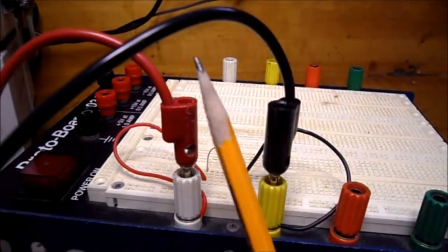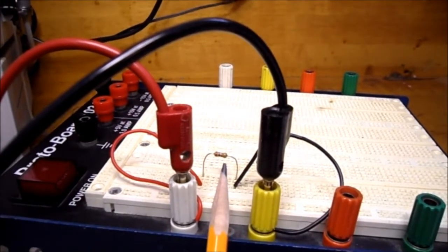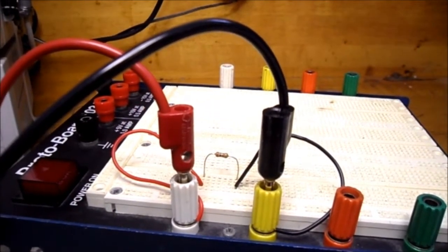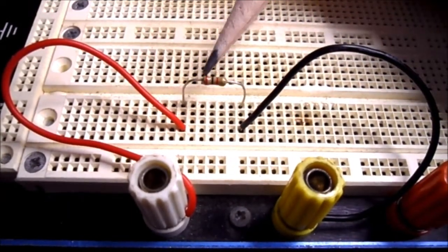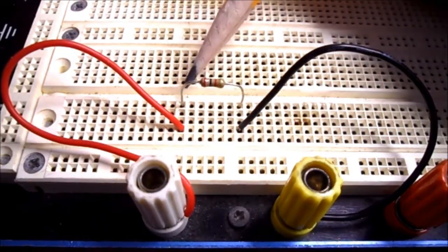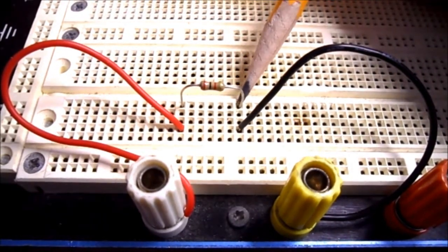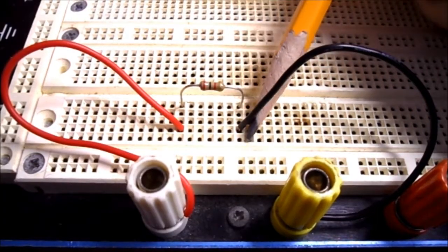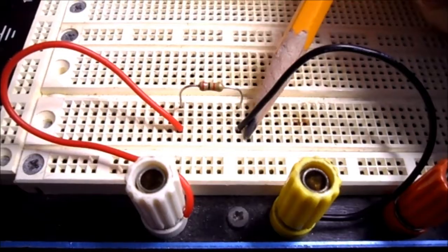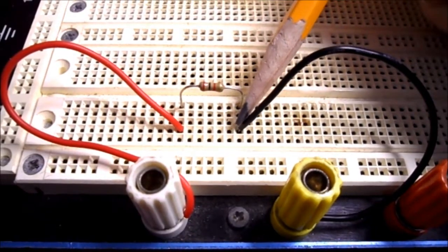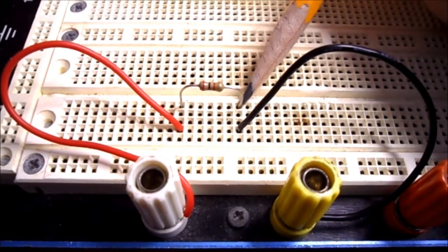And this is my circuit on the trainer. You can see I have one resistor in here. So I want to show you how I wire that up. The first thing I want to show you is this is my 2K ohm resistor. I've got one leg going into this hole and one leg going into that hole. Now these buses are connected across here, so 5 holes are connected together. So I've got the black lead going into the same group of 5 holes as the lead for my resistor.